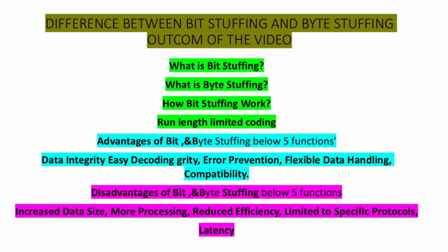Applications of bit stuffing: synchronizing several channels before multiplexing, rate matching two signal channels to each other, and run-length limited coding. In run-length limited coding, the number of consecutive bits of the same binary value in the transmitted data is limited; a bit of the opposite value is inserted after the maximum allowed number of consecutive bits.